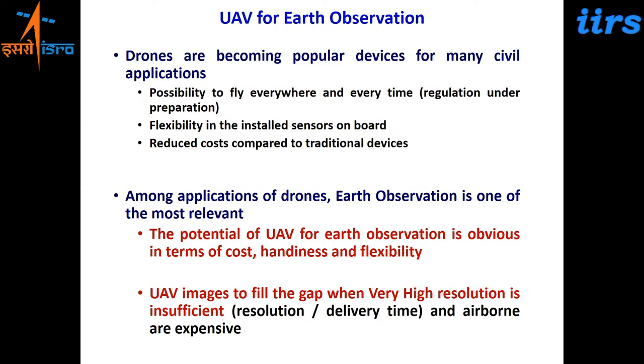In mountainous areas, the issues are the shadows, the areas which are on steep slopes. They are not acquired by the satellite because of their acquisition geometry, their platform geometry, as well as the solar elevation angle. They are collected at a particular time of the day. So sun elevation has a big role to play. Certain areas may be in shadow at that time.